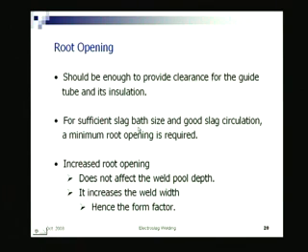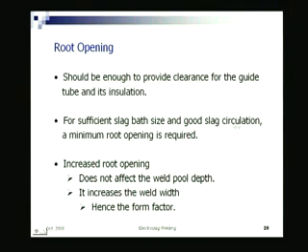Obviously, for sufficient slag bath size and good slag circulation, minimum root opening is required. On one side, it should be enough to have the guide through which the electrode will come. Again, I should look to keep it minimum such that sufficient bath and good slag circulation takes place, right. So, increased root opening does not affect the weld pool width, right.